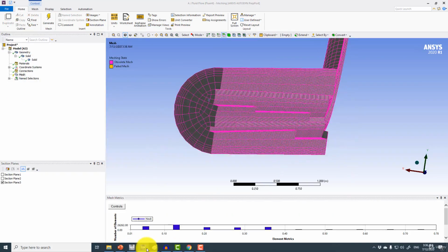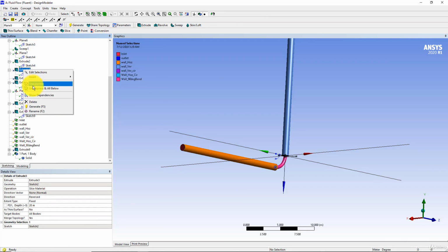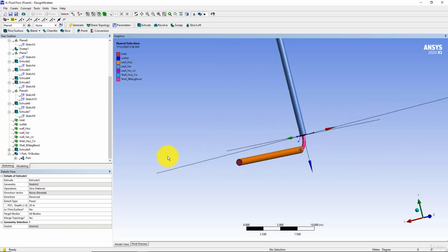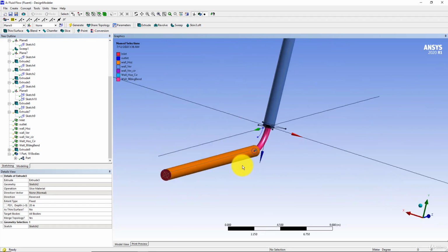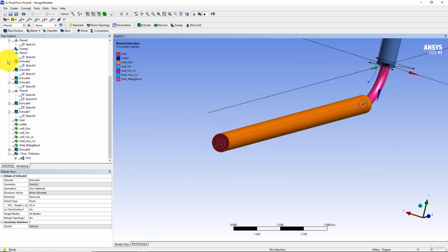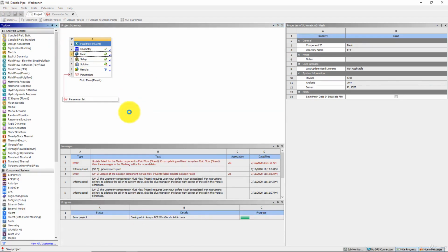Then I will go to the geometry tab. And from geometry, I will turn on all the options which I suppressed here, to create the decomposition geometry, which is necessary for making hexagon meshing inside the Ansys Workbench meshing. And after that, I'm going to Workbench and also try to save the project file from time to time.